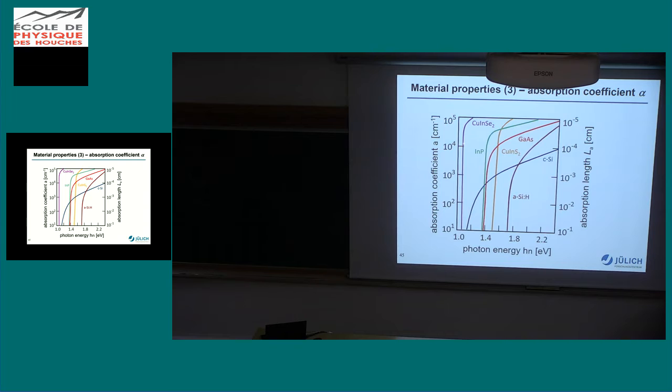So they say it's almost a step function, and if I want to get within a few tens of milli electron volts of such a value, you see that for copper indium selenide, a thickness of 1 micrometer, 10 to the minus 4 centimeters, would be fine to have a good solar cell that is almost as good as a step function for that range.